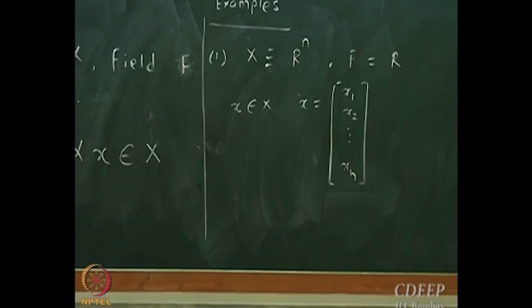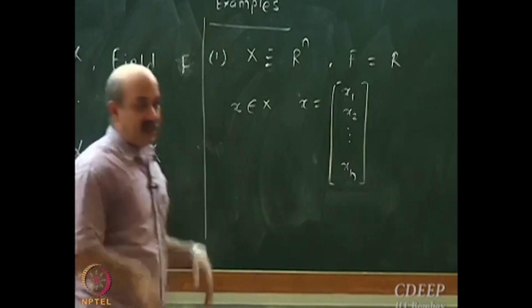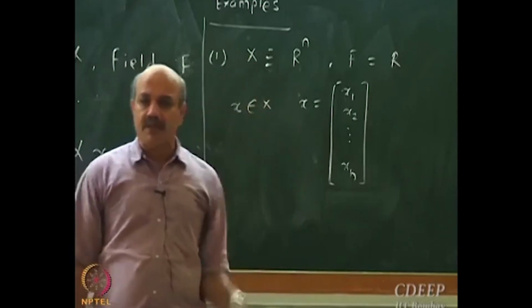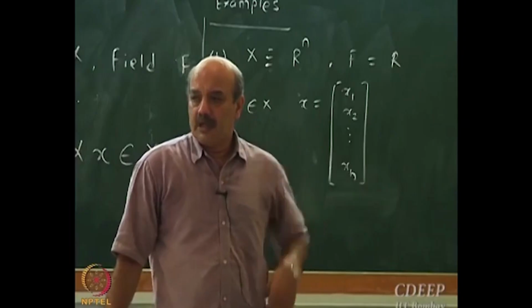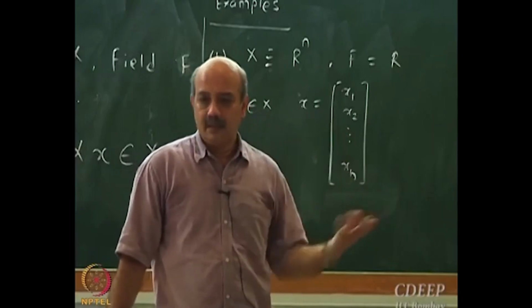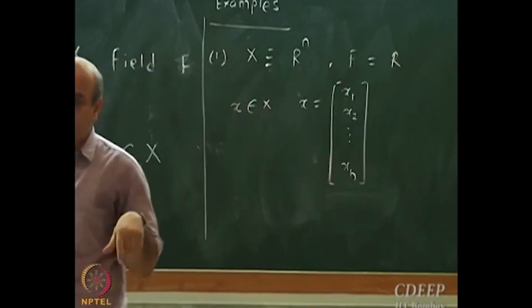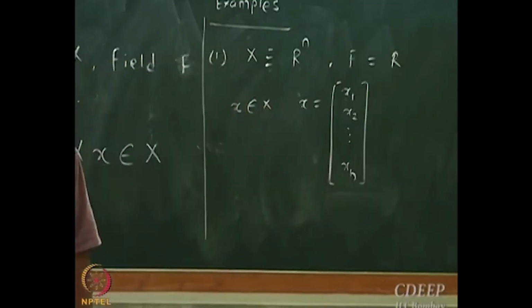So this is a vector that represents the state inside a reactor, or let me take a distillation column. A distillation column will have different trays, and on each tray you have temperature, pressure, composition, right? So if there are 20 trays and it's a binary distillation column, how many variables you expect to have? 20 temperatures, 20 pressures. Actually, pressure will be varying across the column. Then compositions, about 60.